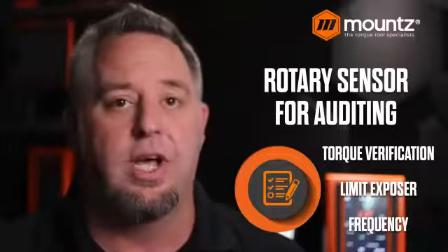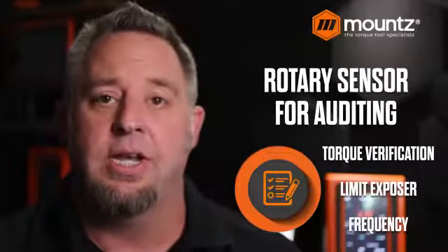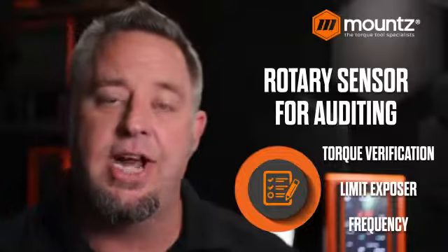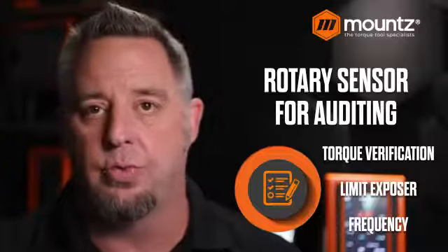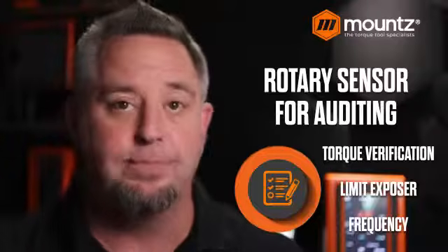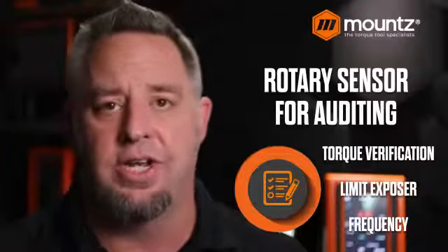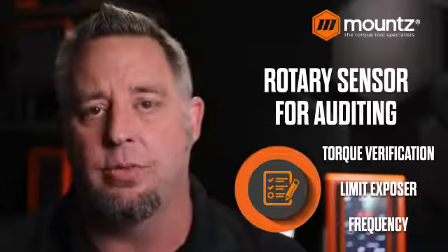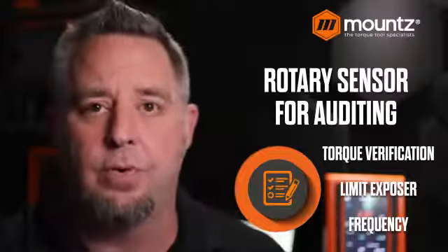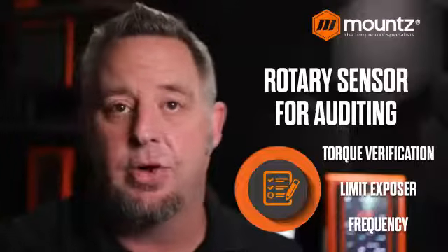And so with this, each sensor has its own specific range. So we can test from about 10 inch-ounces all the way up to 1,500 foot-pounds. And so there are different models within those different settings. So we could test different tools with different torque settings. But auditing on the factory floor is a really primary use for the rotary style transducer, again, helping us to measure the dynamic torque that's being produced out on the factory floor.